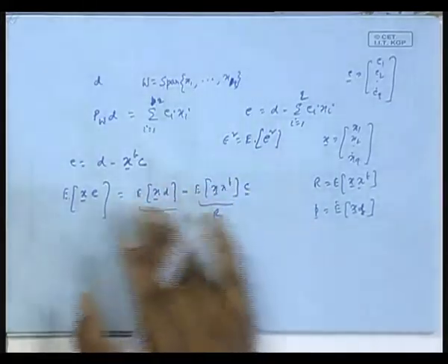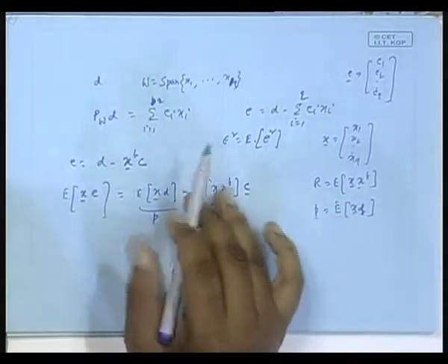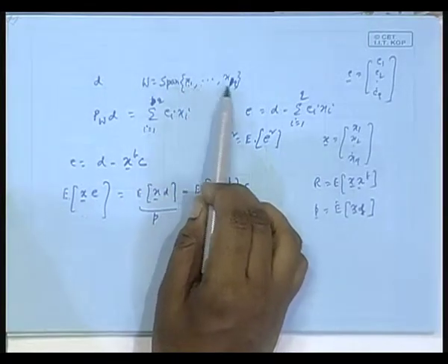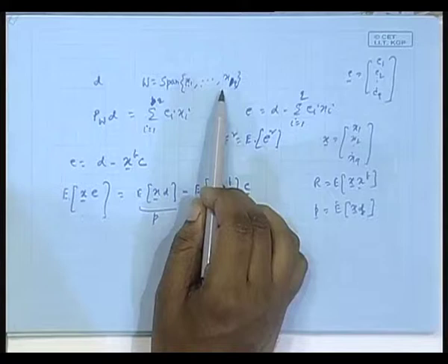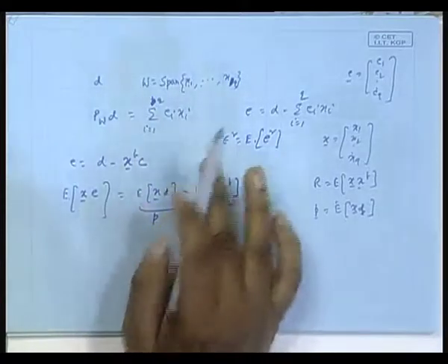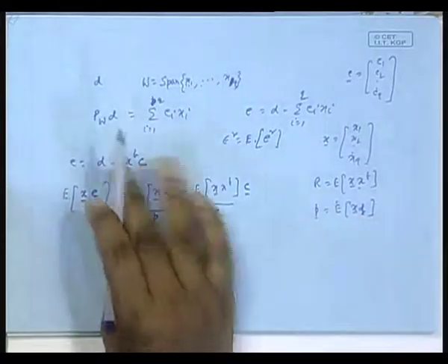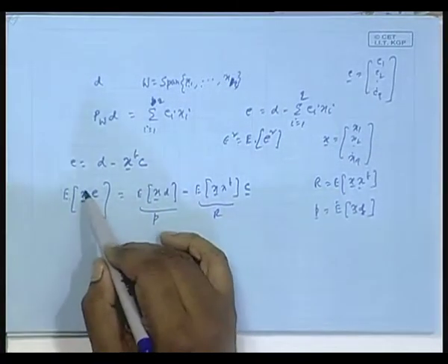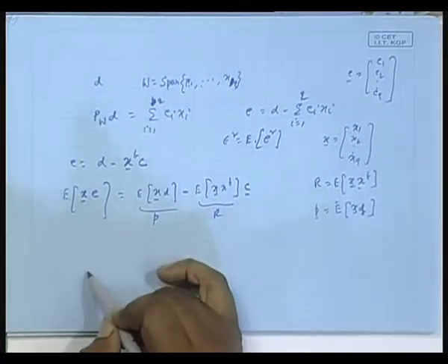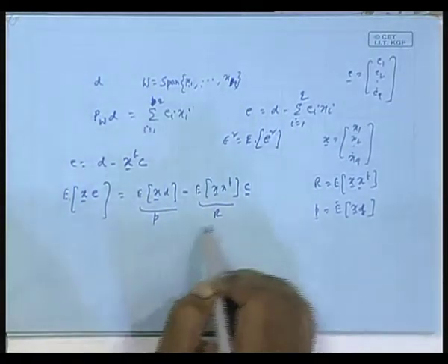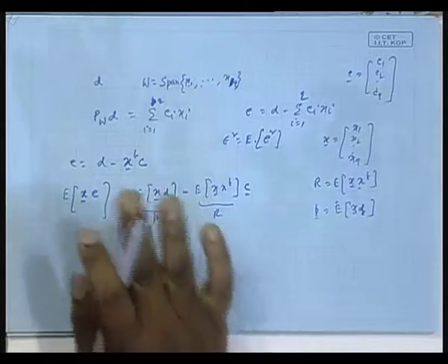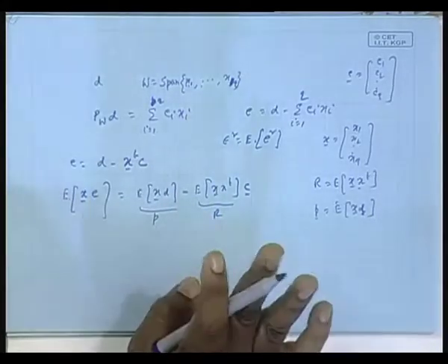This is a slightly more general way of doing things than that filter case, in which case these variables are nothing but x n minus 1 dot dot dot x n minus q here. I am just making it a little general, but the approach is the same. It is orthogonal projection, the error has to be orthogonal to each of the components. So, you put the components in vector form, each correlation term here will be 0, from that you get this equation that C optimal is R inverse P, is not it? This was the thing we started with at that time.